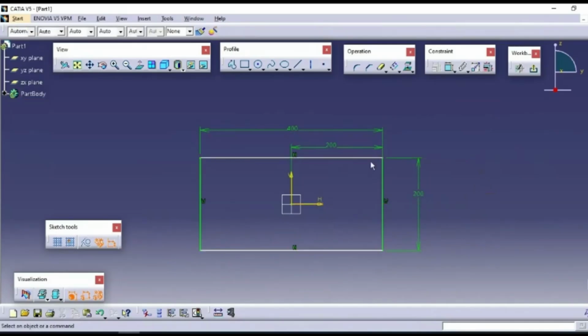So in that case, you can go for another constraint method. For example, this is symmetry, right? That is, these two lines are symmetric about this axis. So these two lines first, then the reference axis, both I have selected. If you want to select continuously, you have to press Control. Otherwise, if you select once and then select another, the first will be gone. So press Control to keep selecting. Two outer edges and the reference axis. Now you can see the first tool is enabled.